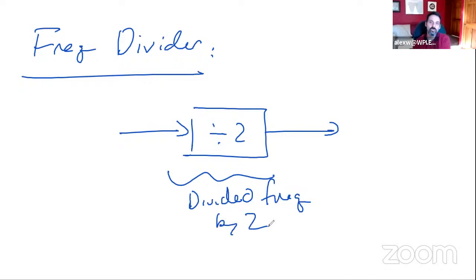We used this a few lectures ago, where we had a double frequency term that we were extracting using a bandpass filter to remove the DC terms, and then we used the frequency divider to halve its frequency. This is exactly the same thing: if we had a wideband FM signal and wanted to make it narrowband, we would divide the frequency, in this case by half.